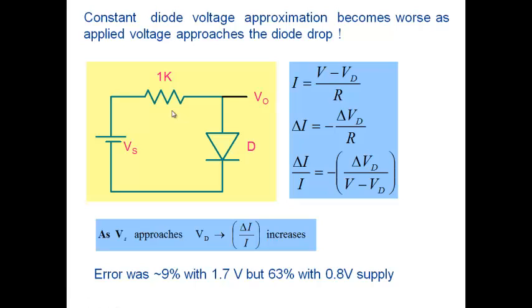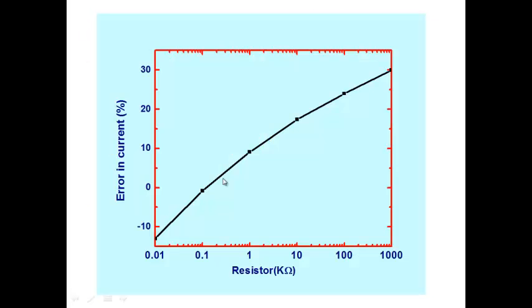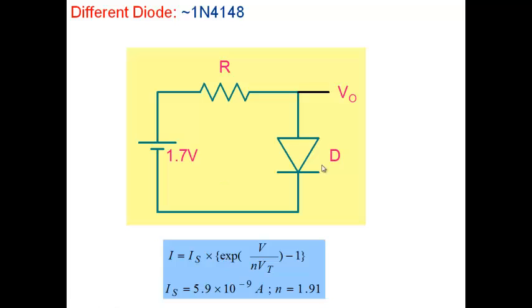Okay, so you have to assume what? Maybe you have to assume, let's say, the diode drop is 0.6 or 0.5. Suppose I assume that the diode drop is 0.5. It's arbitrary. 0.7 minus 0.5 divided by R will give me a current. And once I know the current, from this equation I can recalculate a better diode drop, which may turn out to be 0.6 or 0.5 or whatever. And with that you do the calculation.